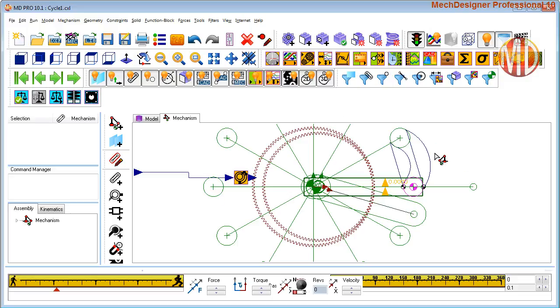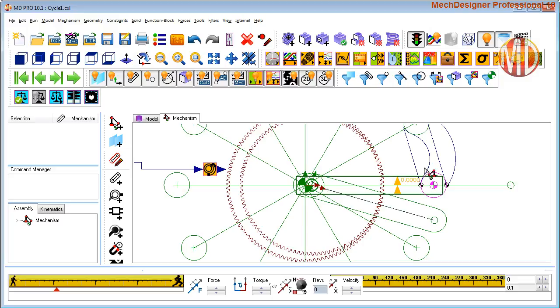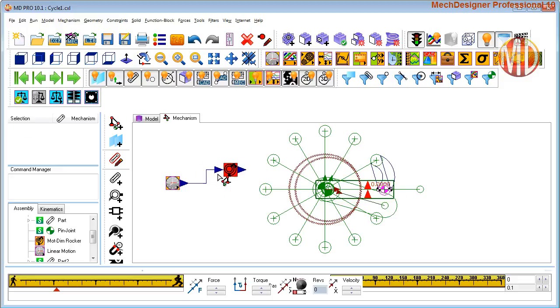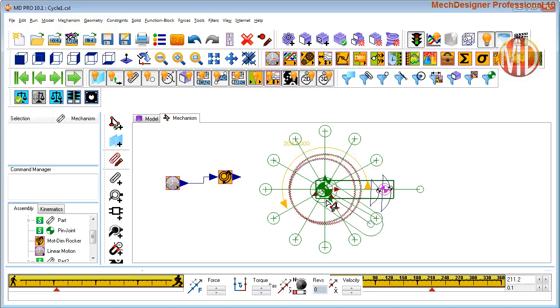Now, it doesn't look much like a cycloidal, but you'll see here there's a start of it, but it doesn't seem to be doing much. So to show it doing all 11 cycles, and as it happens, this will do 1 rev. If I just cycle the mechanism, 1 rev of this crank is actually 1 lobe pitch. And what we want to do is cycle this 11 times within 1 machine cycle.